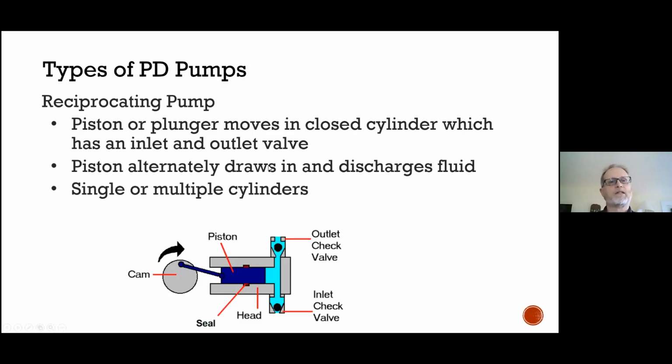So a couple of examples of positive displacement pumps, and they may have different construction, but the principle is the same. On a reciprocating or piston pump, here's the piston in dark blue, a shaft or a cam turns, and the piston moves back and forth, and every time it pulls back, water is pulled into a chamber. When the piston closes, water is pushed out. Then the cycle is repeated. A fixed amount of water, or any fluid really, is brought in, and the cycle repeats. It can do this at very high rates of speed, typically though with quite small volumes of fluid.